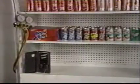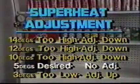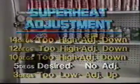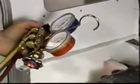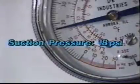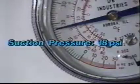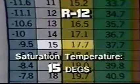The adjustment of the superheat setting on a thermostatic expansion valve is a relative setting. This means that to make any new adjustment to the setting, you must first know the superheat resulting from the existing setting. To determine existing superheat, we need to know the saturation temperature, which can be found by measuring the suction pressure. The pressure reading should be taken with an accurate suction gauge as close to the thermal bulb as possible. The suction pressure reading should then be converted to saturation temperature with a temperature pressure chart.